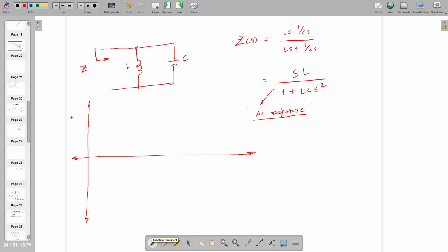Okay. The magnitude plot will have magnitude in dB with respect to frequency, might be in radian per second or might be in hertz. So you cannot forget the Bode plot. Sir, the zero was minus 20 dB, right? Zero is plus 20 dB per decade. So 1 zero will contribute plus 20 dB per decade and one pole will contribute minus 20 dB per decade.